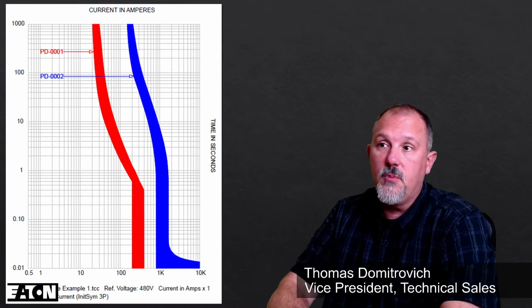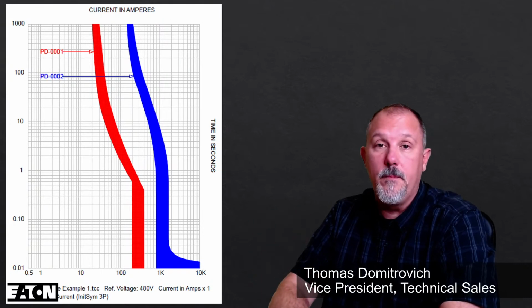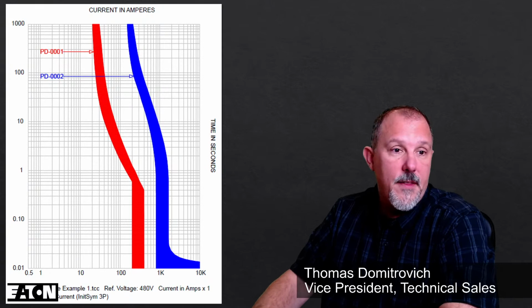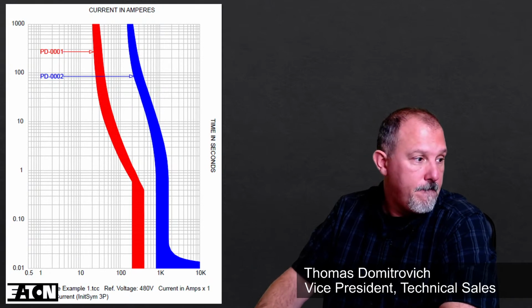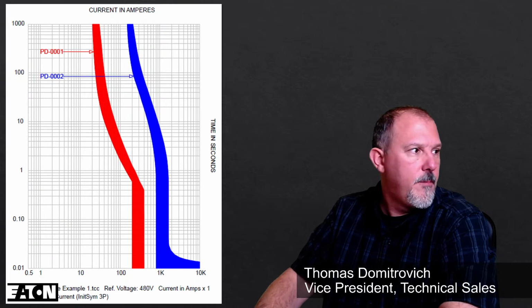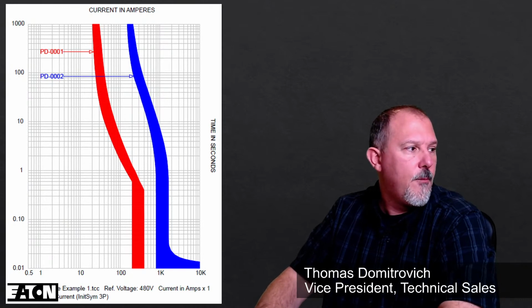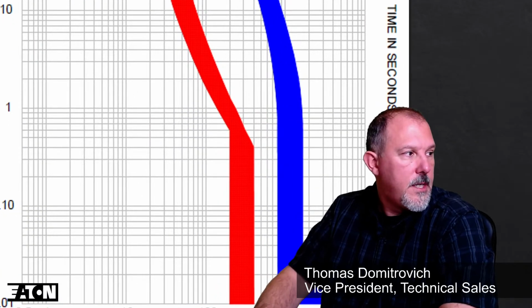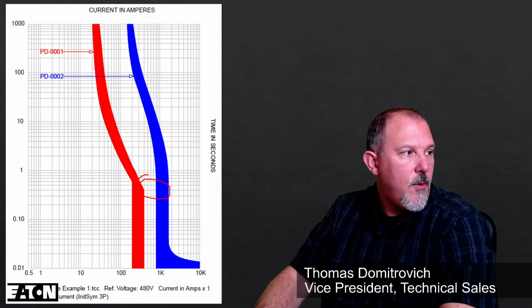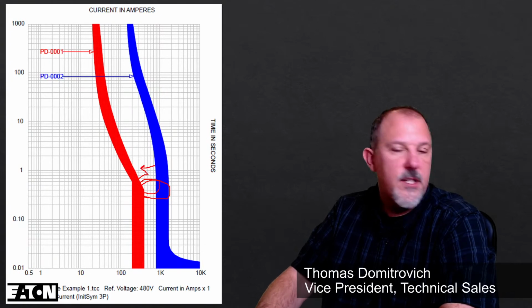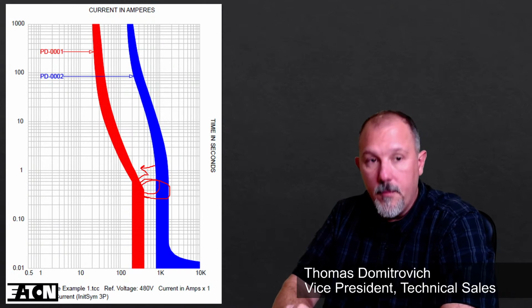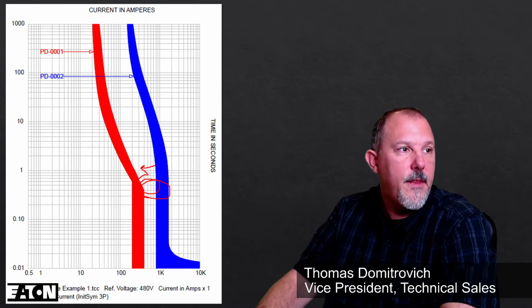So I can put a very small breaker, which is what I'm doing with the F100 breaker. All I'm looking for is separation of those curves. The only area that I'm really worried about in reality is, you might get a blip there, right in here at the knee. So if I'm only worried right here in that knee, I can take this circuit breaker and make it smaller and smaller. As long as I don't bump into that knee, I am perfectly fine. I will meet the coordination requirements that are in 517.